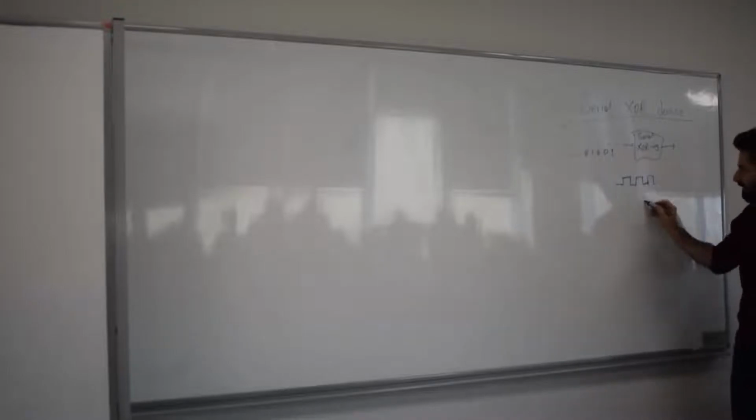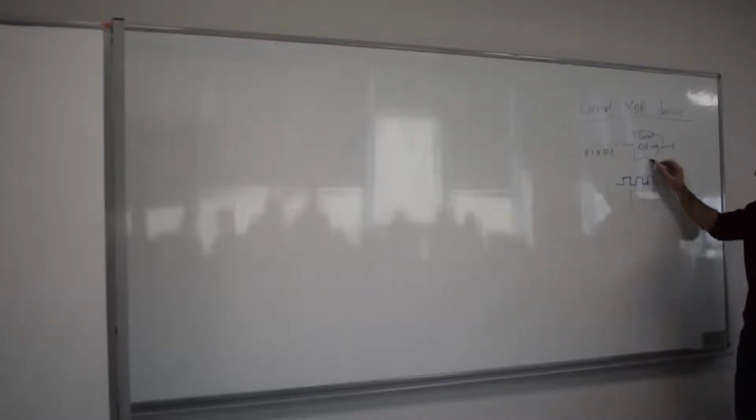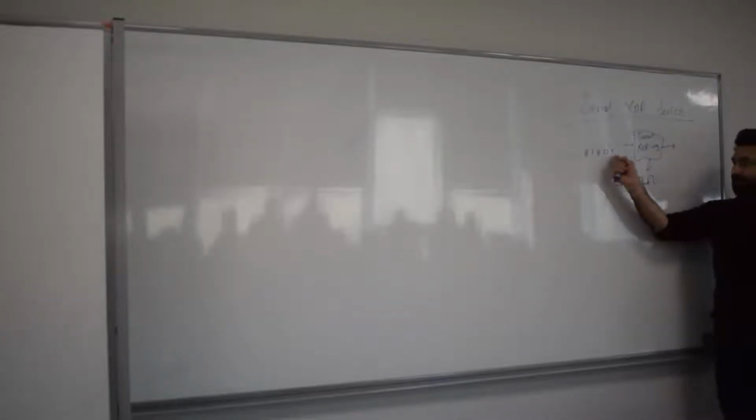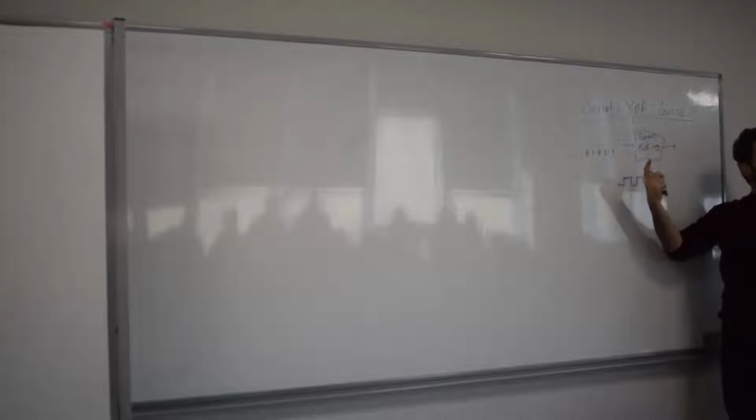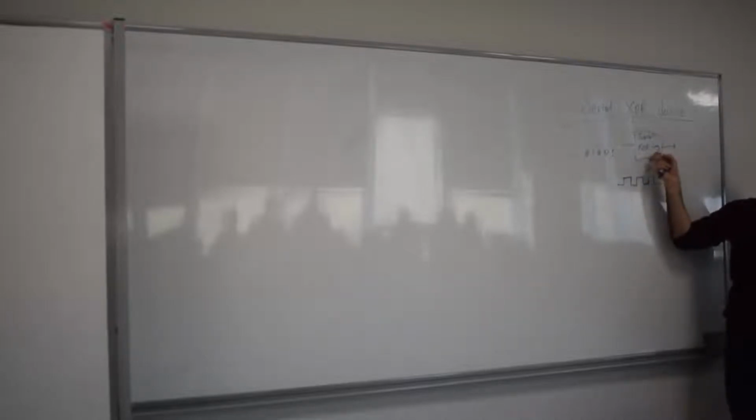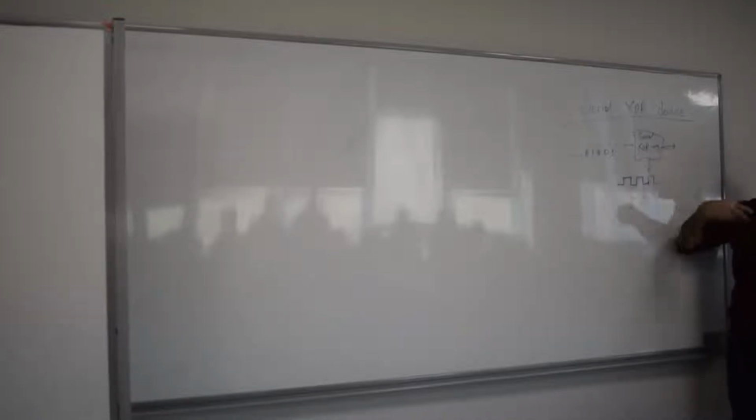All right? So every single period here is one operation, right? And in every single one of these periods, you XOR the incoming bits to what? To your state. Your state is going to keep the XOR of all the bits that this device has seen already.